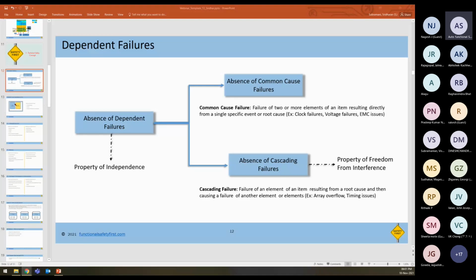We would have to consider the nature of the system and the complexity of the safety software. What tasks does it have? Does it have interrupts? Does it need any deadline monitoring, like does something have to execute within a certain time? If it needs those kinds of timing faults to be detected, then just having a watchdog will not be sufficient, and we would need a health manager to detect the additional timing FFI faults.